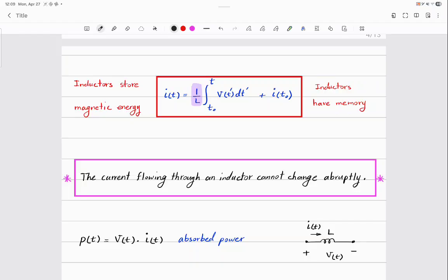The opposite of the fundamental equation that we had is the integral equation, for when you have the voltage and you want to find the current. One thing that students sometimes forget is to multiply the integral by 1 over L. You can either use integration, or if these are geometric shapes, you can just calculate the area. Remember, above the horizontal line is positive, below is negative, and when you're calculating the area, you're only calculating the integral.